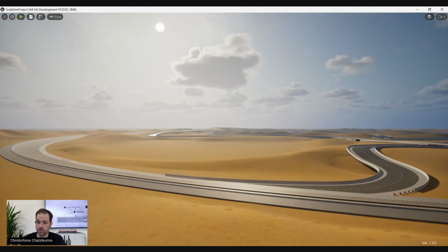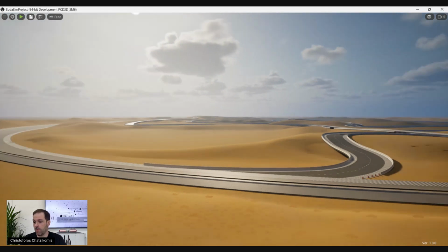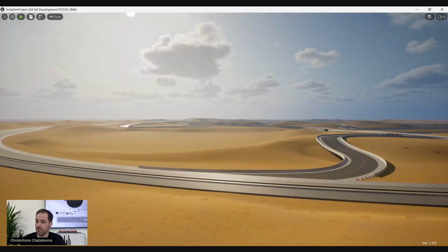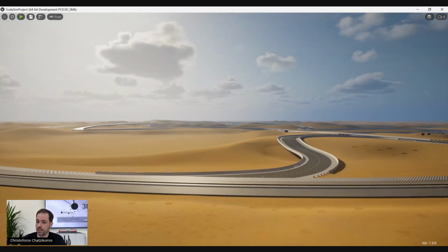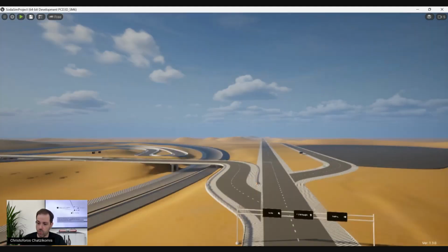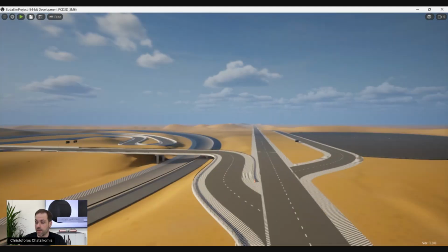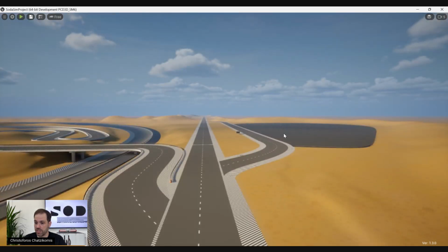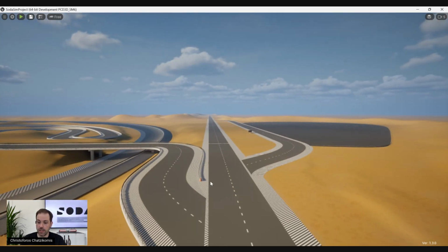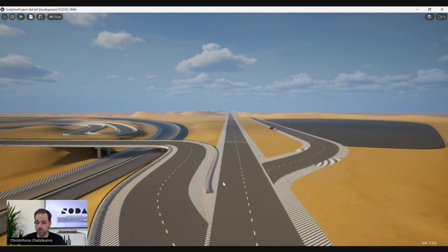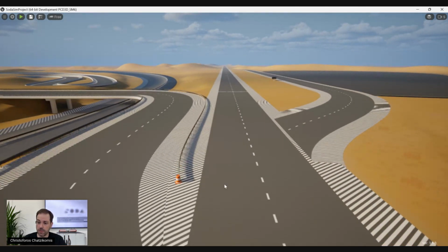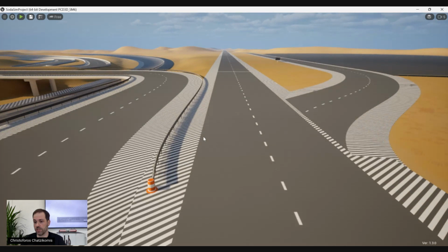The virtual proving ground includes a high-speed bowl for high-speed vehicle testing, testing the handling of the vehicle, a very long 1 mile straight that can be used for straight testing, and a very large skid pad area for any relevant testing. Today we're going to use our straight line to set up a vehicle avoidance test, to show you how quickly you can set up a test if you want, for example, to test the vehicle dynamics.